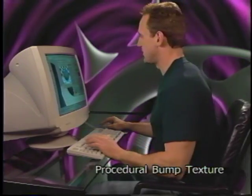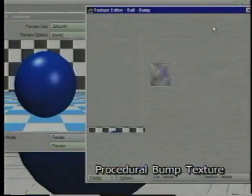The texture editor, you'll find that in many different places. So as I'm editing a texture on transparency, it'll be the same texture editor that I use on the bump channel, which is also the same texture editor I might use on a volumetric light. So once you're familiar with the generalized texture editor, you're all set all the way throughout the app for any kind of texture editing. So in this case, we're going to go ahead and change our layer type to procedural.